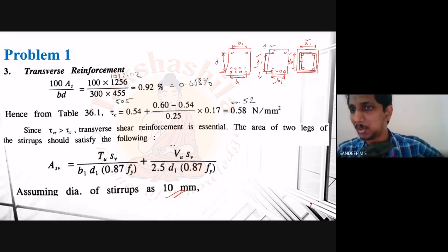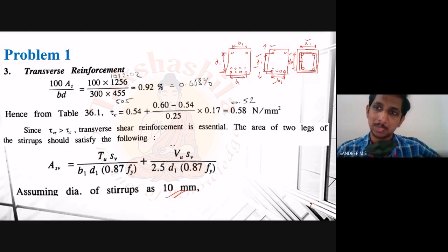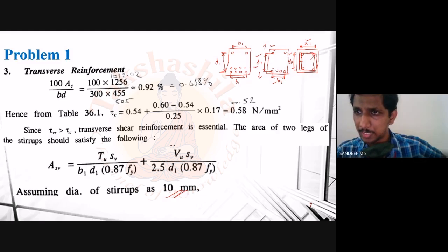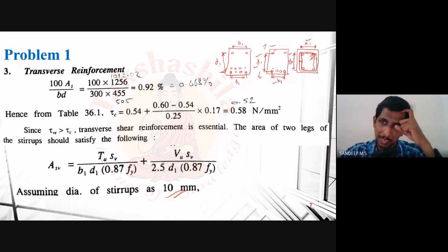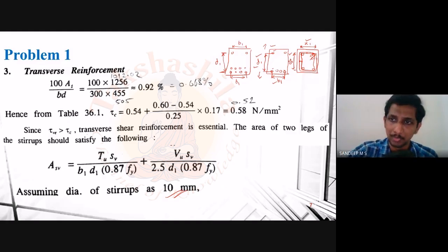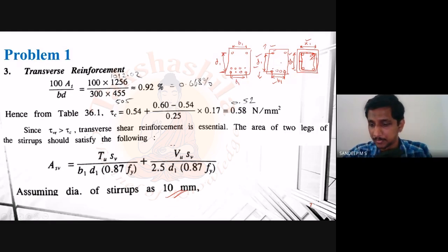So you have basically your longitudinal reinforcement and your stirrups running around that. It is a loop, closed loop actually provided around the longitudinal reinforcement. So in order to calculate x1, you have to take the center to center distance like this. Center to center distance in the shorter direction means it is this one, and center to center dimension in the longer direction means it is your y1. Is the concept clear? Any doubts in that? Okay, I assume that you have understood that.